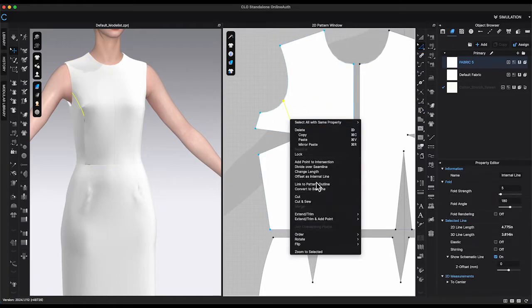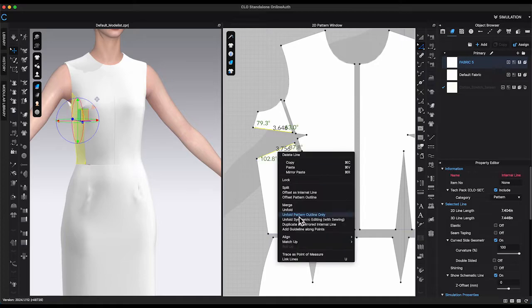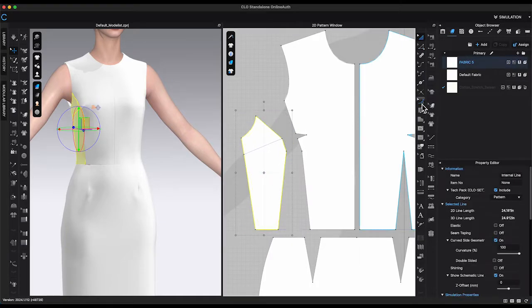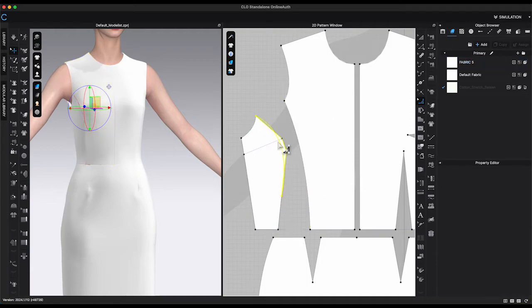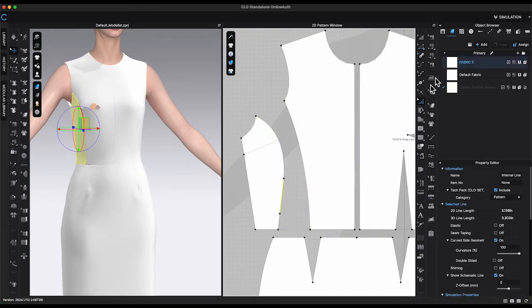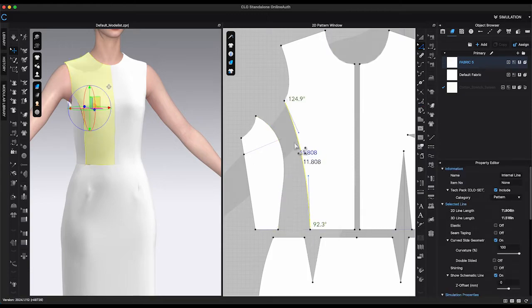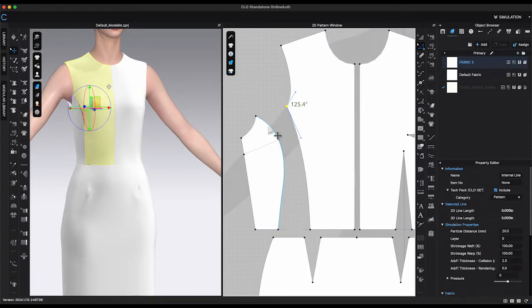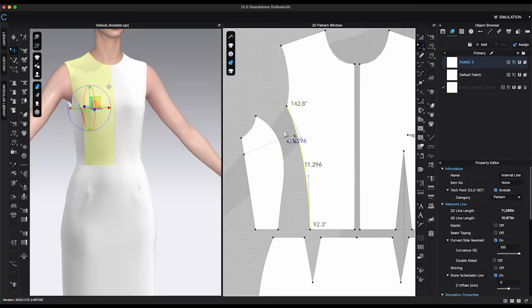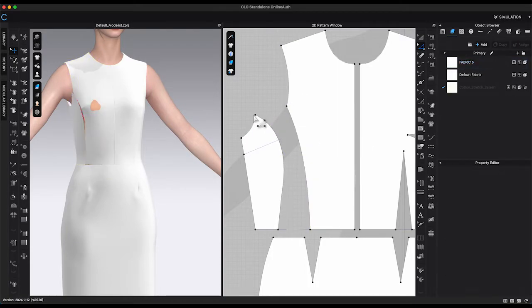On the avatar, I have uploaded a basic woven fabric dress block. For the upper bodice, I am using stretch satin fabric. To make it more fitted, I will create 2 princess seams. Because I am going to apply 2 large lace trims in the center front later, I will move the princess seams closer to the sides to avoid breaking the lace design.